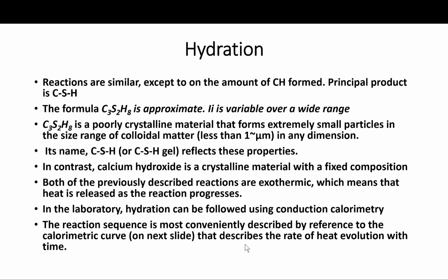So remember that, especially when we are dealing with large concrete sections. In the laboratory, hydration can be followed in a special calorimeter. I talked about this when we talked about the tests on cement, by monitoring the rate of heat conduction needed to keep the temperature constant.